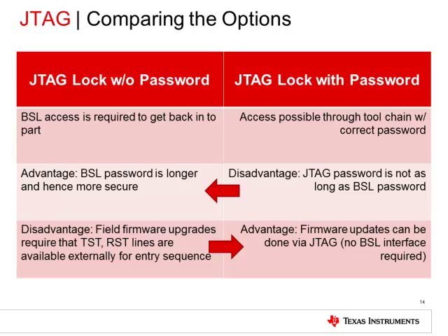is required. The second option, securing JTAG with a password, involves generating a unique password that is stored in the IDE such as CCS or IAR. When the device is accessed from an authorized source that is able to provide the correct password, JTAG access is made available once again.